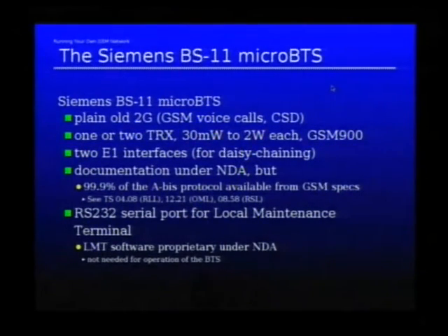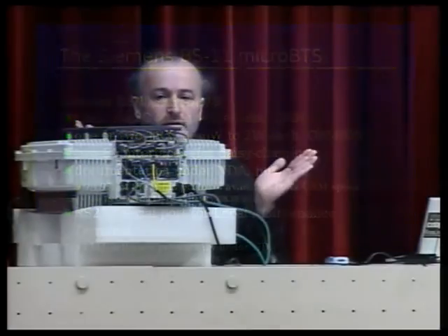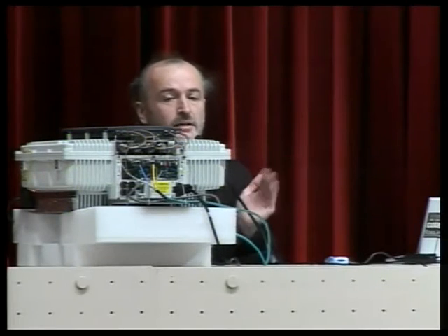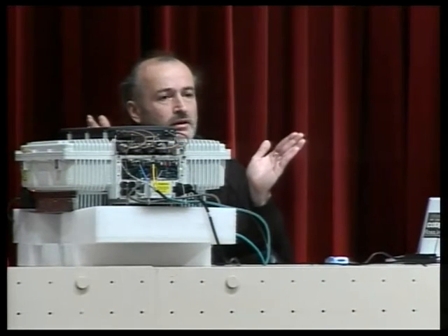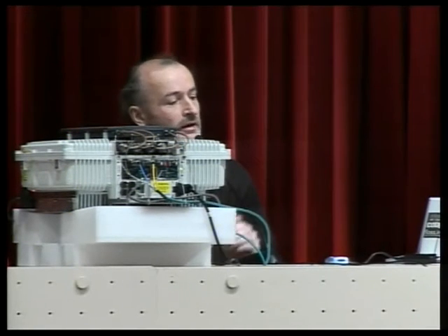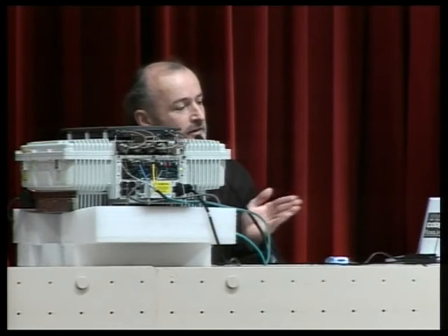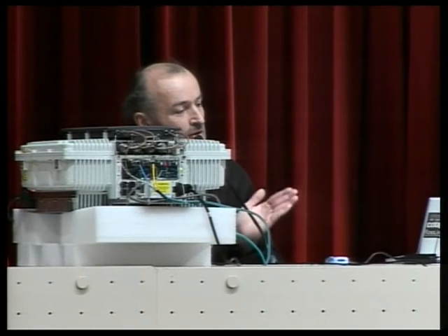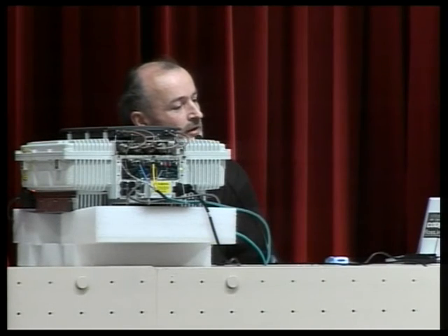You should not use the 2 watt because this is the power similar to your phone, so you will have a really huge range. The antenna is a directional antenna, so you usually have roughly 180-degree transmission direction. But anyway, I would suggest if you try it, turn it down to 13 milliwatts.